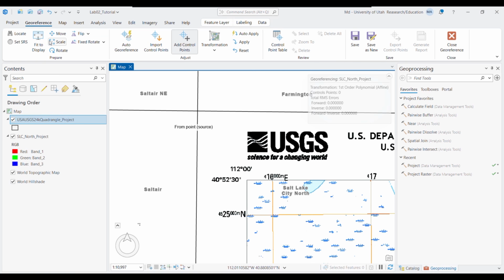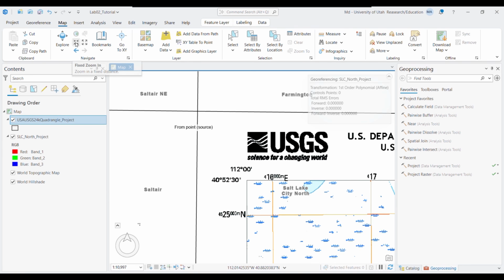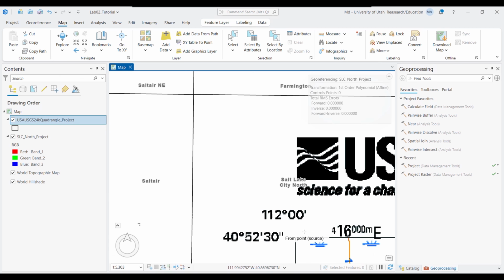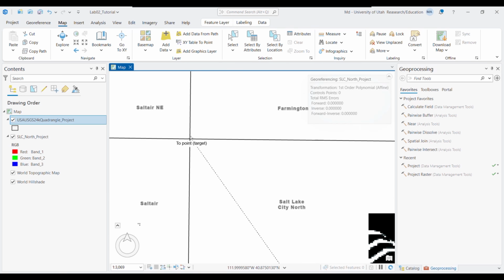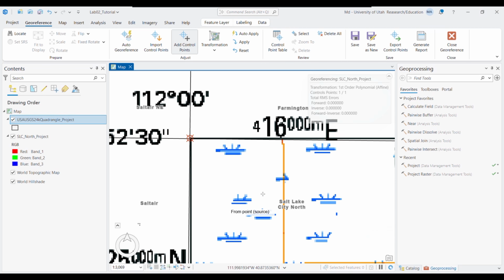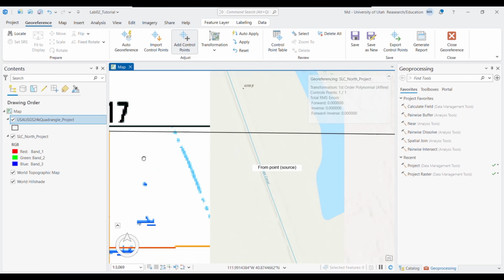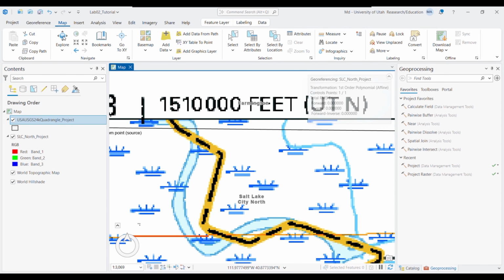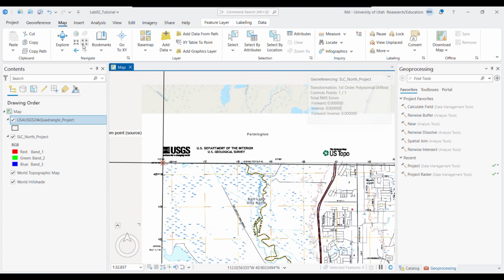This point has to be at the intersecting point of the topographic map. So we are clicking on our image and clicking onto the point of the topographic map where we want our point to be located. Now if you click on Apply, it will be applied and you can see that our image has been moved towards its correct place.